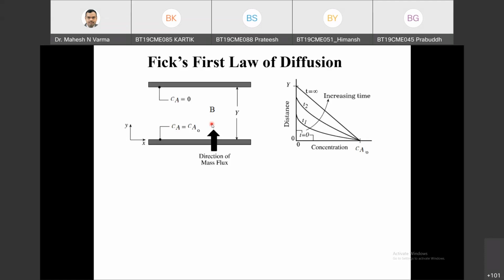So it is the duty of a chemical engineer. The chemical engineer is the only engineer who deals with both mass transfer and kinetics. Now you need to decide whether your system is governed by kinetics or by mass transfer. How are you going to decide? Whether it is convective mass transfer or molecular mass transfer, zero bulk motion is not the case in mass transfer. You will not get any mass transfer with zero bulk motion. If velocities are very, very small, it can be categorized into molecular or conductive flux. If velocities are very, very large, it will be categorized into a convective flux in mass transfer.